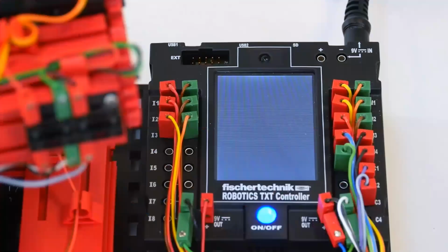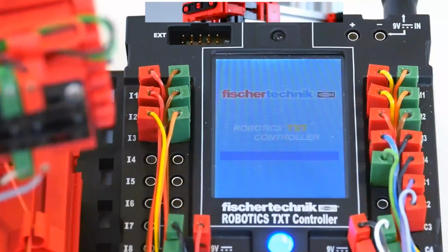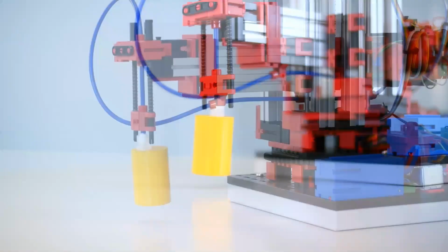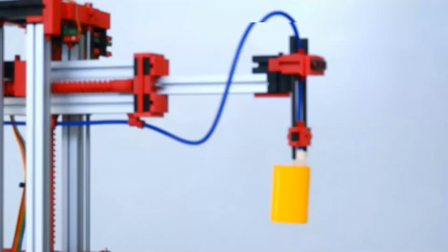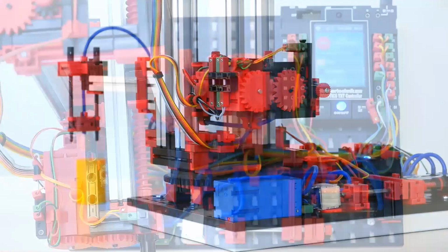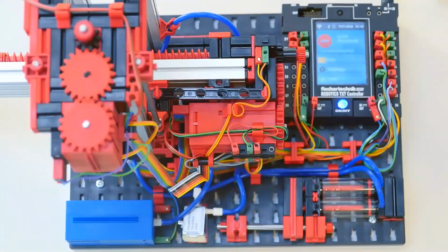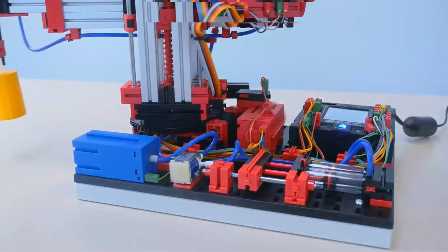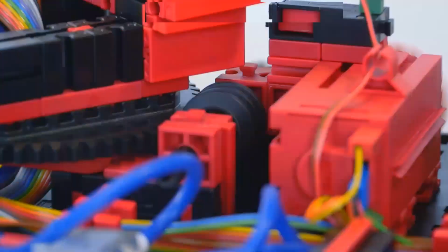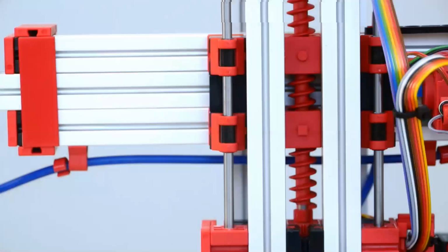The 24-volt versions of this model, as well as all the other 24-volt models we will look at later, each have a relay board for motor polarity reversal and both a multi-pin connector with 26 pins with a grid of 2.54 millimeters, as well as additional PCB terminals with push-in connections for all inputs and outputs. Again, the 24-volt version of this model, as with all 24-volt versions, will require you to provide the PLC and